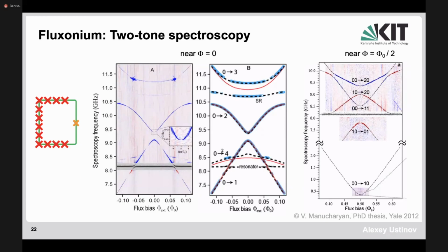And by using this resonator at a frequency which is detuned, for example, you go to the state with 0 flux, then the resonator is strongly detuned, but nevertheless, the excitation of the qubit due to existing coupling will still be shifting the resonator dispersively, so one can use the resonator for the readout.